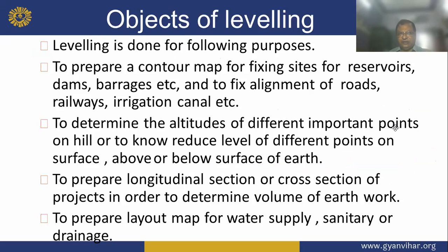Now, object of leveling. Leveling is done for the following purpose: to prepare a contour map for fixing site of reservoirs and dam and barrage, etc. Thereby, if you will not draw the contour map, you cannot observe how much water is available in your reservoir. See this.